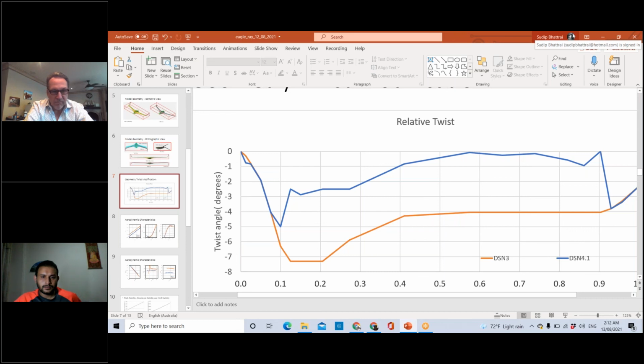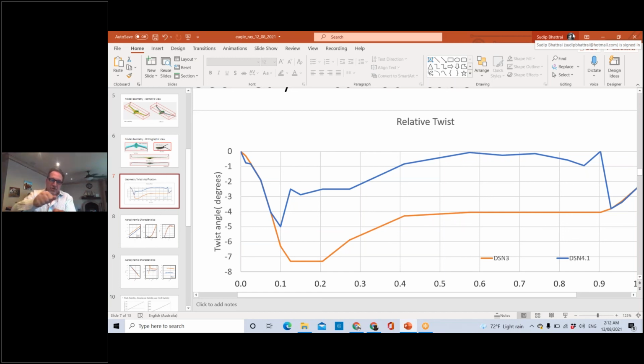So just now, when you're talking about the bank angle stall, is that a standard technique we can follow? Yes. So typically we did spiral test. So yeah, sorry, go on. Yes. So the FAA and EASA and other certifying agencies, when you're certifying big airplanes, you do straight ahead stalls and you do turning stalls, or so-called accelerated stalls, because the stall happens earlier.